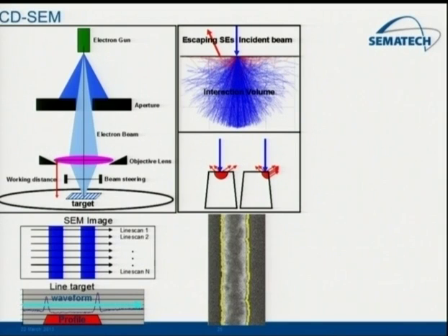Now, the reason I mentioned precision and accuracy before is, as you can see, depending on the beam conditions, these peaks in the secondary electron emission may or may not directly line up with your profile. But as long as you've calibrated that at least once, you can probably make an estimate if there is any bias between the waveforms and the actual physical profile. I guess I should explain that a little more clearly.